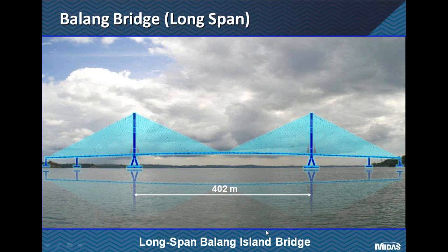Because of such a long span of concrete girder, an intermediate pier was designed in each side span for deformation control and stability reasons. The connection between the pylon and the deck is proposed to be a longitudinal movable bearing, while the intermediate piers are connected to the bridge deck by 8 viscous dampers.